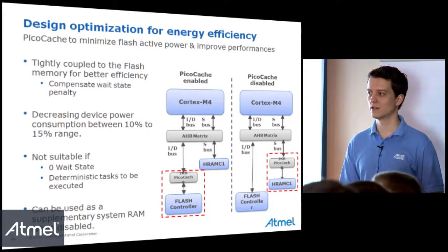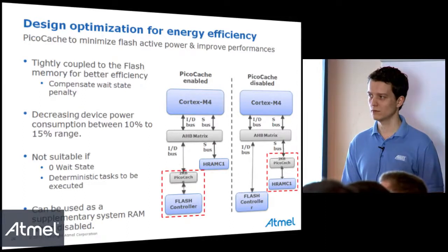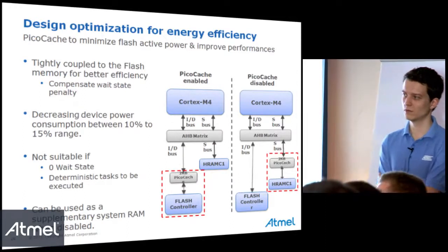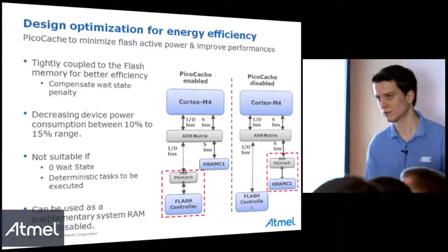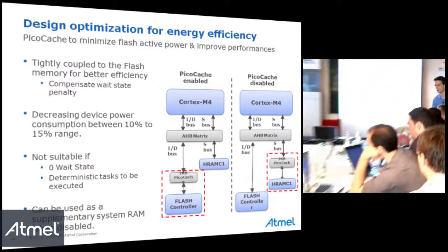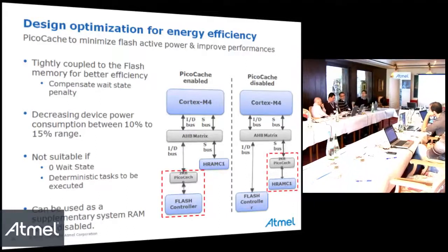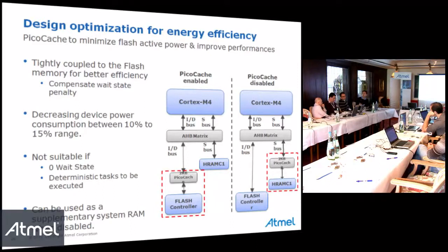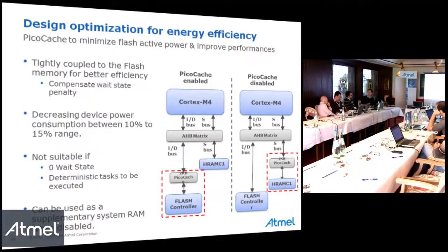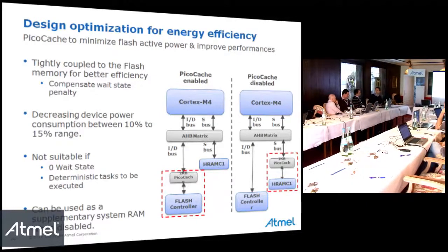Just to add something: for sequential calls, as Jerome said, your statement is valid. But as soon as you have loops and branch instructions, then the cache is useful. It's only in the case of sequential calls that you can anticipate the next instruction thanks to the 64-bit buffer. But as soon as you do a branch, you have to flush, and so then the cache is useful.